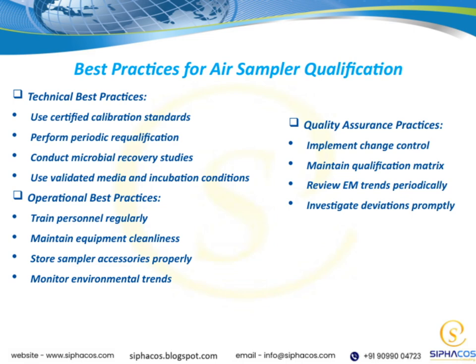Moving on to best practices for air sampler qualification, there are some technical points to highlight. Using certified calibration standards ensures our instruments are accurate. Performing periodic requalification confirms ongoing reliability, and conducting microbial recovery studies helps us validate that our samplers can effectively detect microorganisms. Additionally, using validated media and incubation conditions guarantees that our microbial testing is consistent and trustworthy.